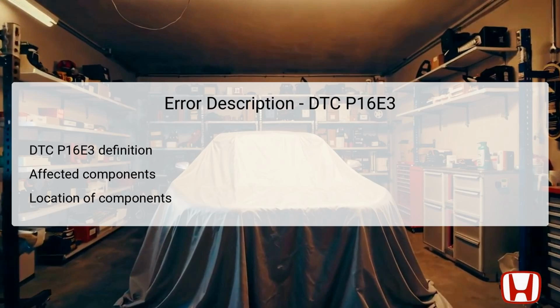The 12-volt battery sensor is typically located near the vehicle's battery, fastened securely to the battery terminal, making it accessible for inspection. The PCM can generally be found within the engine bay or under the dashboard, depending on the model and configuration of the vehicle. A clear understanding of these components' roles and locations helps facilitate more effective troubleshooting.